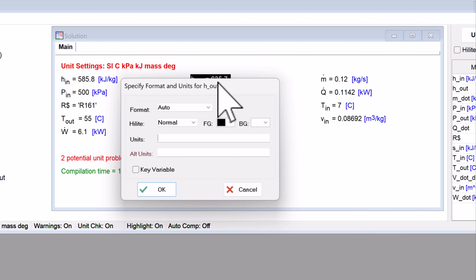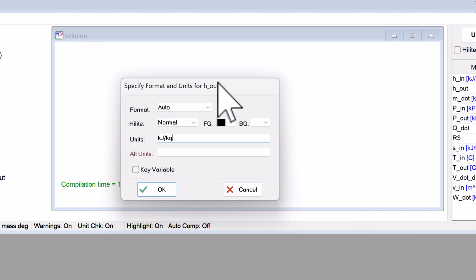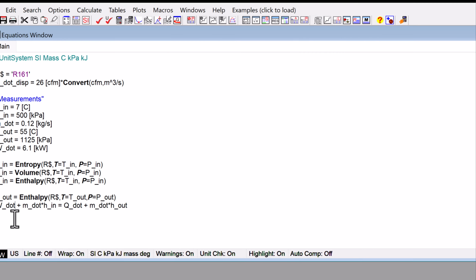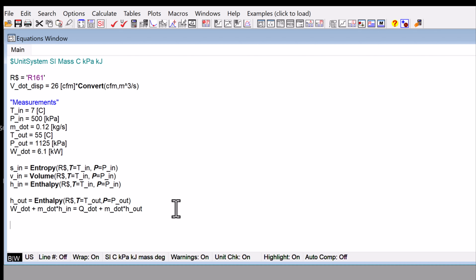And probably I need to set the units of the enthalpy here as well. Alright, so that's one of the things I have to calculate. The other two things are the efficiencies, the volumetric and the isentropic efficiency. So the isentropic efficiency is based on comparing the power to the power required by an adiabatic reversible compressor. So that would be one where entropy doesn't change.